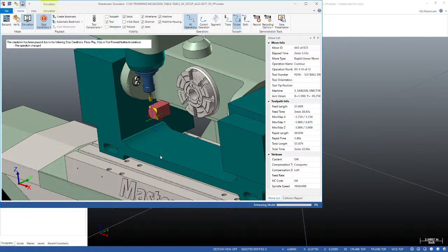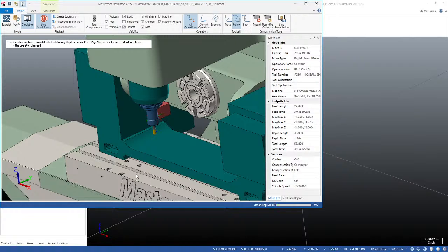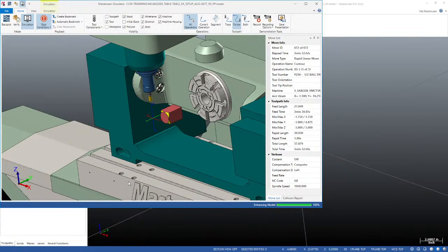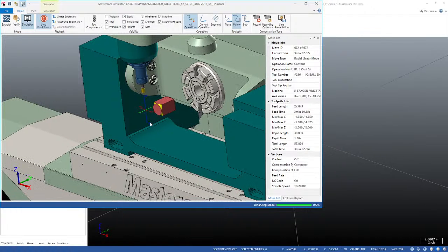One of the things that's happening is it's going from the start of each toolpath to the start of the next toolpath without necessarily retracting and without changing orientation before it makes the move. So we end up having to ignore the fact that we're seeing some collisions that are created, because we don't actually get to see what's happening between these cuts.